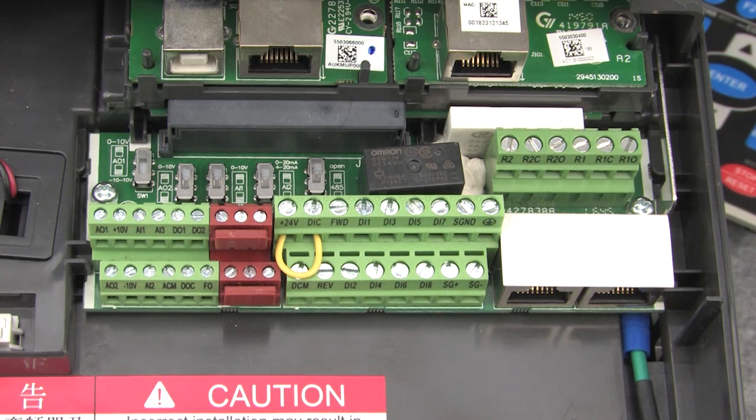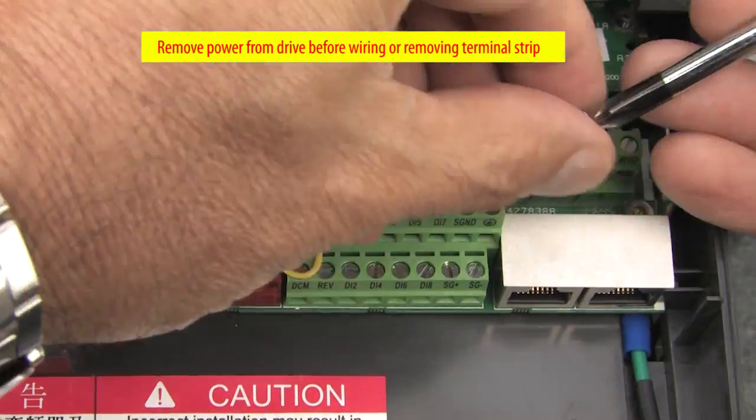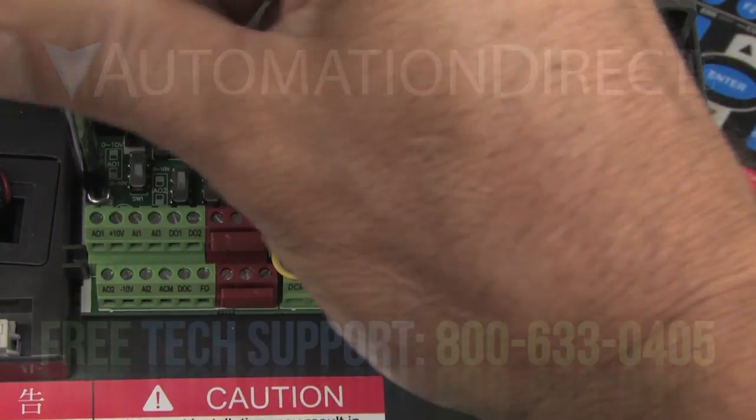The analog outputs are located here on the terminal strip, and remember, if you remove these 2 screws, you can pull out the terminal board to make your wiring easier. Then just slide it back in, reinsert the screws, you're ready to go.